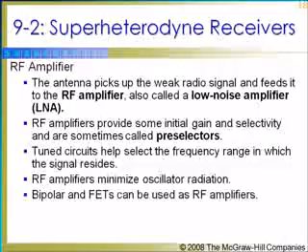The tuned circuits in fixed-tuned receivers can be given a very high Q, so that excellent selectivity can be obtained. The tuned circuits must resonate over a wide frequency range. Therefore, the Q, bandwidth, and selectivity of the amplifier change with the frequency.